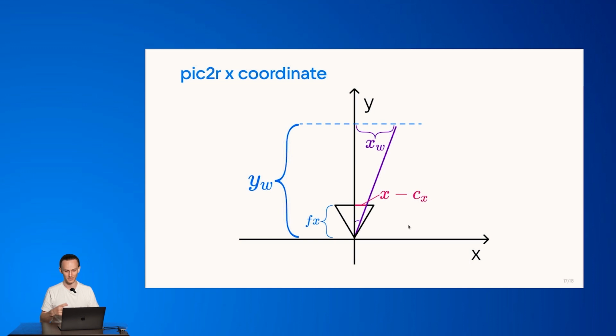Here, basically the same thing is going on with the world model. We're subtracting the coordinate of the center of the photosensitive matrix from the x coordinate. That gives us, dividing this whole thing by f sub x, the tangent of the angle. Basically, these two triangles, this small one over here, that is measured in pixel units, and this one that is bigger, they are proportional. That, with the basic ratios, gives us the x sub w coordinate, and we're happy because we have calculated the real-world positions of the object that is lying on the floor.